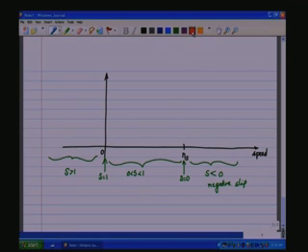So when slip was greater than 1, we said that it is in the braking mode. In braking operation, the speed is negative, the other direction compared to the rotating magnetic field.